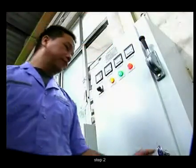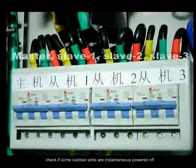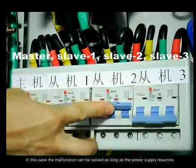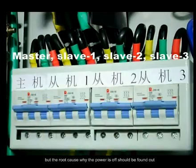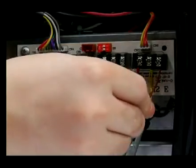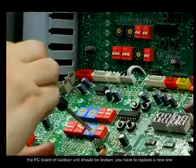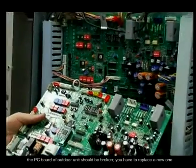Step 2. Check if some outdoor units are instantaneously powered off when there are many modules in parallel connection. In this case, the malfunction can be solved as long as the power supply resumes, but the root cause of why the power is off should be found out. After the above repairs, if the malfunction still exists, the PC board of the outdoor unit should be broken. You have to replace it with a new one.